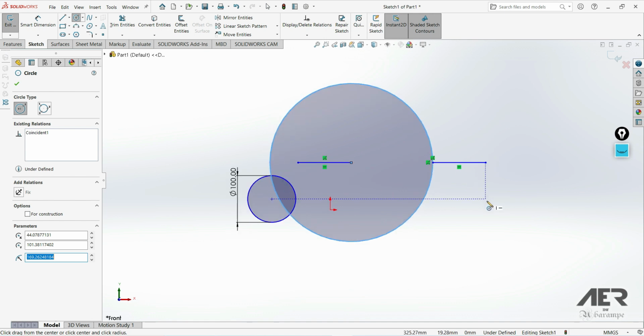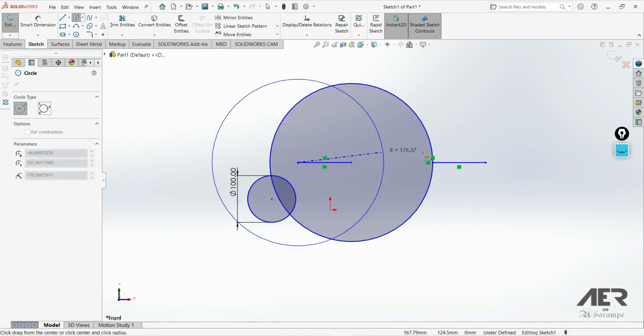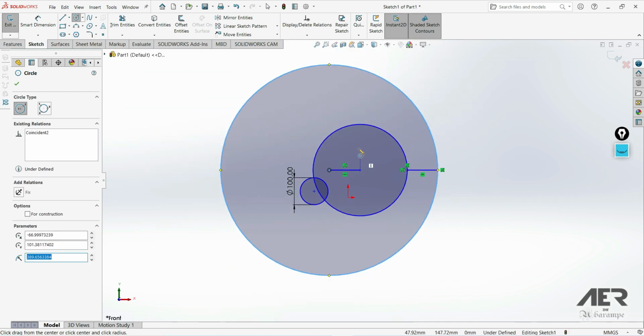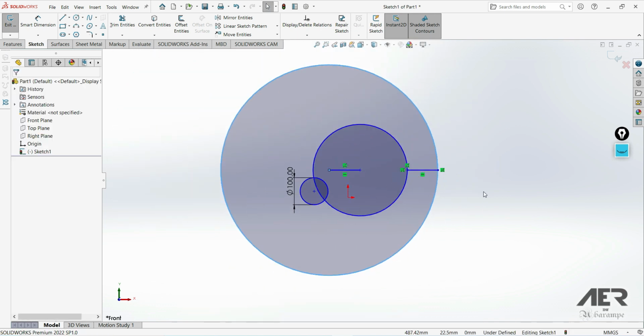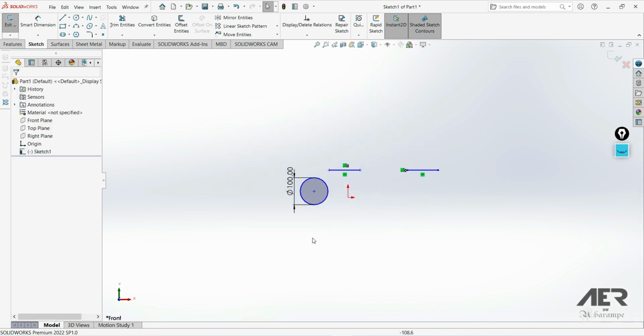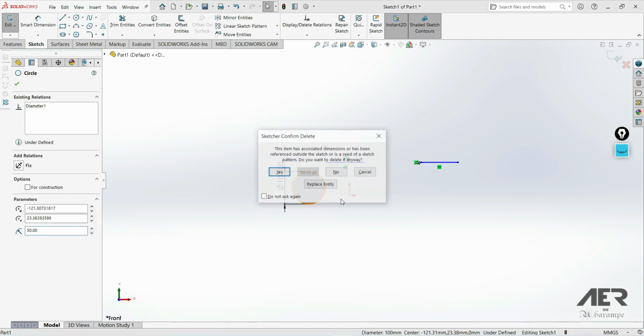So it's not necessary that all the time we have the diameter or radius value. Sometimes we have to take references, and at that time we can use these kinds of methods. Like, let's say one more example, from this endpoint to this endpoint, I can just create a circle accordingly. Now this is an approach of circle in which we should have the center point.